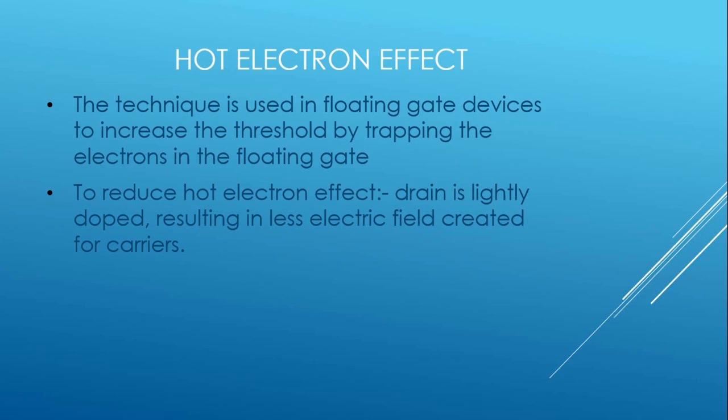That means a device with two gates, one external gate that we normally have, and one floating gate. They purposely made a few hot carriers within the device, and they catch those carriers in their floating gate. You can check out its working. I just told you the technique they use in the floating gate.